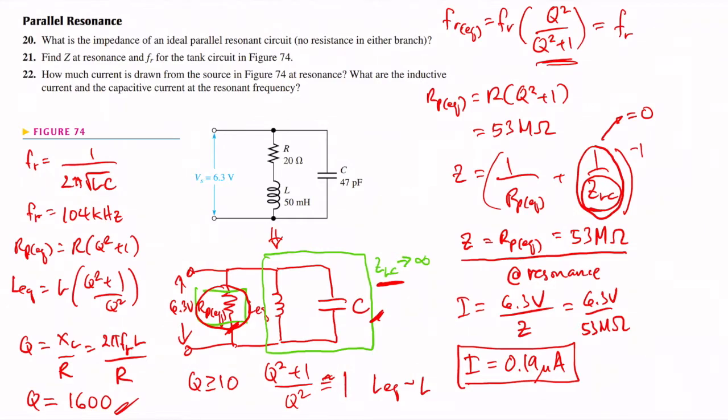Now let's solve for this current. What we're going to do is solve the current at each branch. So we're first going to solve the current here. In order to solve for the current there, we need first to get the capacitive reactance. And once we get the capacitive reactance, we then solve for the capacitive susceptance. We know that they are just reciprocals of each other.